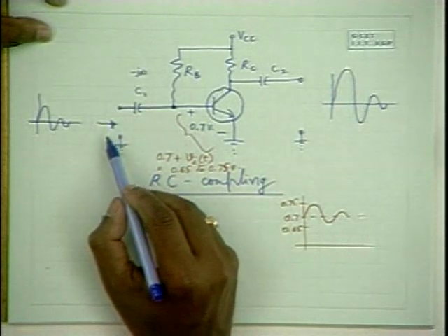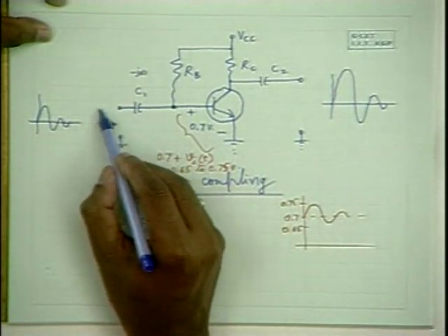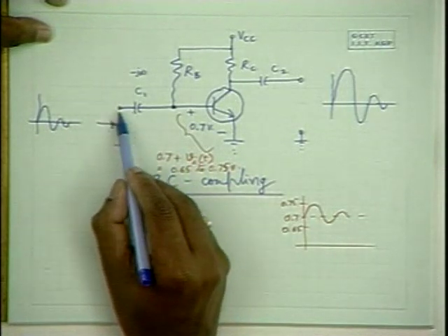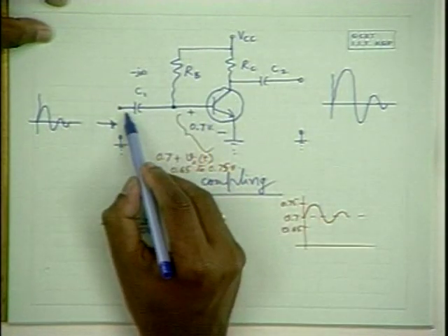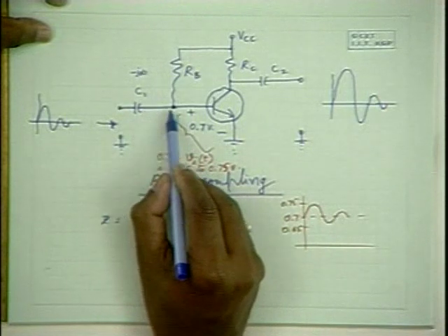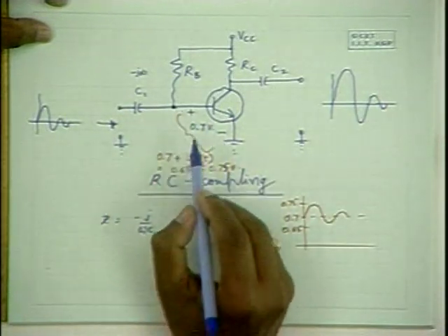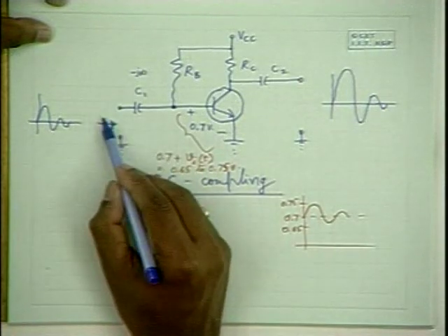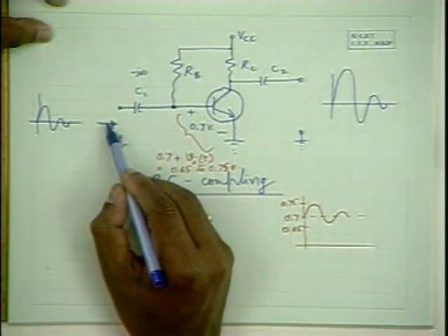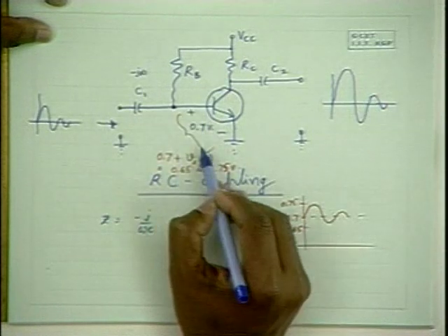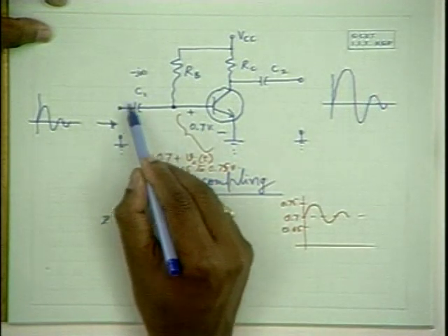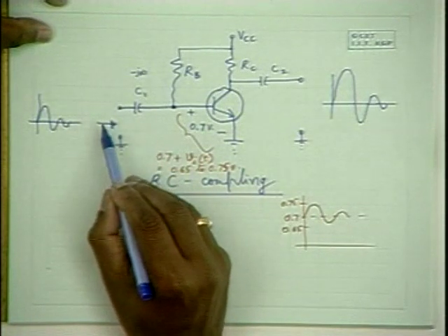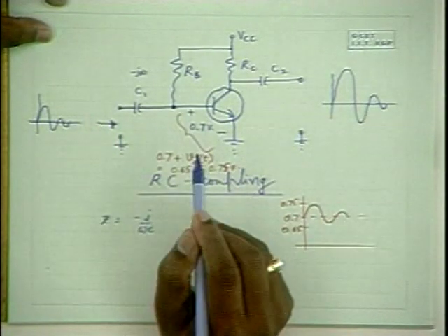So this alternating signal, which is supplied from the source, is connected to this base to emitter through a small resistance in this fashion. It has a high internal resistance Ri. Now you have Vi here. So now Vi gets divided between this impedance, and this is negligibly small. Therefore, all this voltage is applied across this.